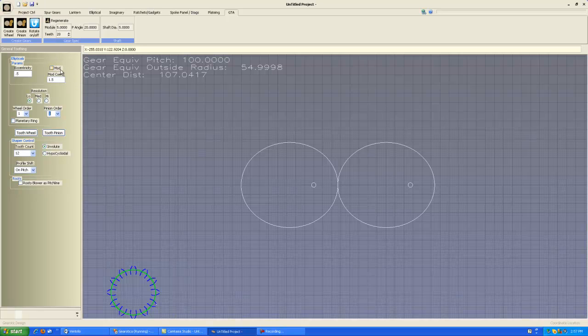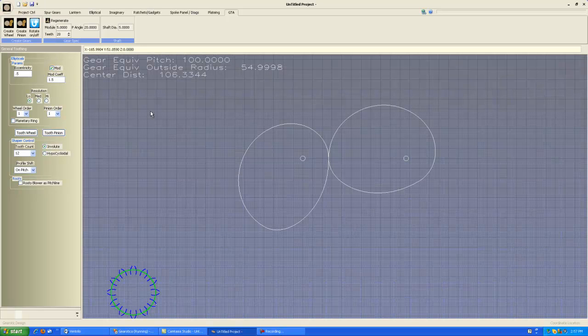But now you can also have a modified elliptical which changes the symmetry of the gear. So the gear is no longer symmetrical top to bottom. And this creates a lot of challenges in terms of meshing two gears together. You can see that these gears, while they do mesh, they don't mesh at a 90-degree angle to each other. So everything gets a little bit strange when it comes to seeing exactly how they'll operate in terms of speed.